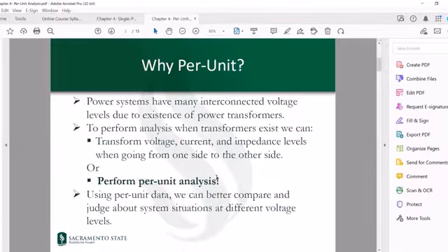By doing the per unit analysis approach, instead of using the units of voltage and current and ohms, we're going to use all the numbers in per unit, which means that when the per unitization has happened on a consistent base level, you should not worry about using the right unit of voltage, or transferring one current from one side to the other side, or transferring one voltage from one side to the other side. These will not be of your concern anymore. You just do the calculations using those per unit numbers, using KVL and KCL, and that's it.